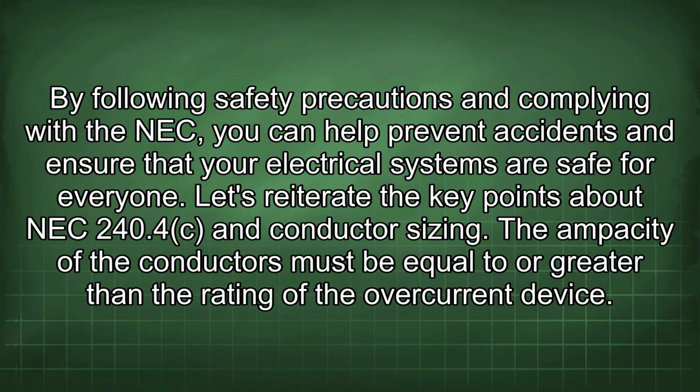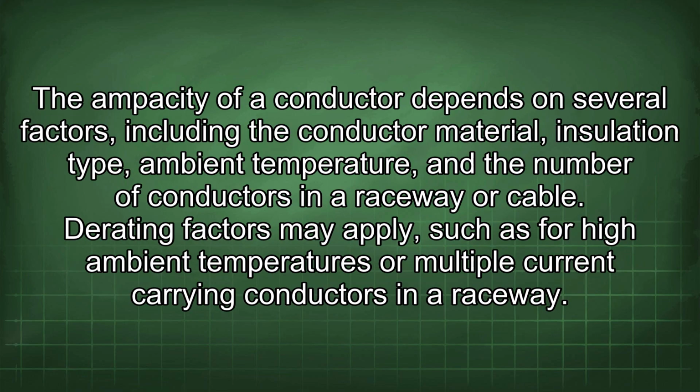The ampacity of the conductors must be equal to or greater than the rating of the overcurrent device. The ampacity of a conductor depends on several factors, including the conductor material, insulation type, ambient temperature, and the number of conductors in a raceway or cable. Derating factors may apply, such as for high ambient temperatures or multiple current-carrying conductors in a raceway.